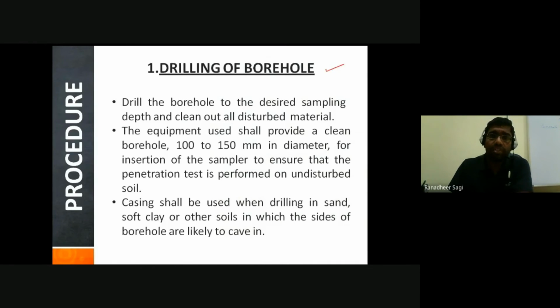So to start with, how do we conduct this SPT test? First we need to make a borehole to the required depth, at whatever depth you want to perform your SPT test. Sir, in a particular site, is it only at one depth that we perform the SPT test? No. At whichever depths you want to perform your SPT test. Let's say, for example, first I want to know the SPT N value of the soil at a depth of 2 meters. Then I want to know the SPT N value of the soil at a depth of 4 meters. So what I can do is first perform the SPT test at the depth of 2 meters.